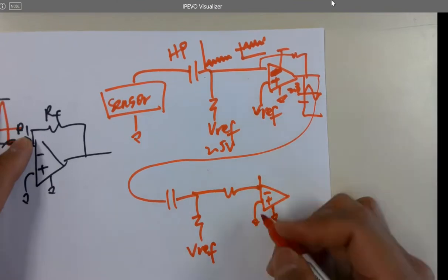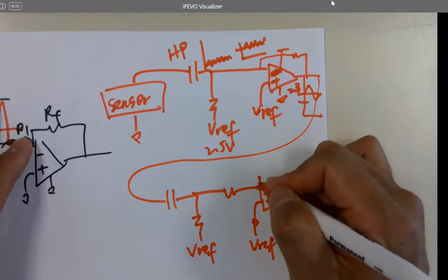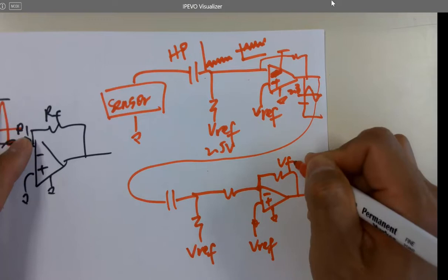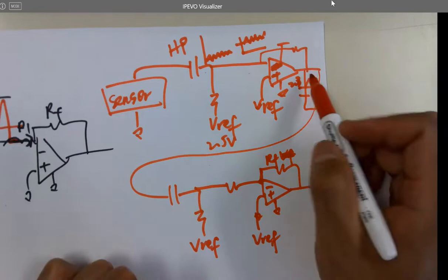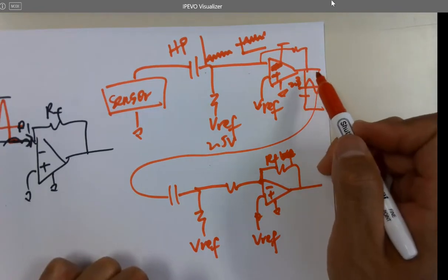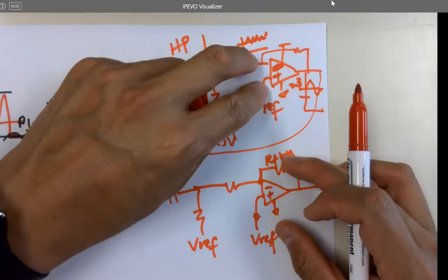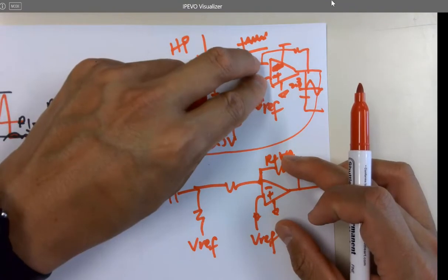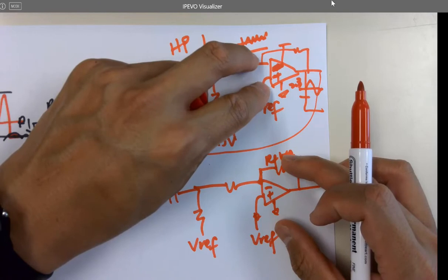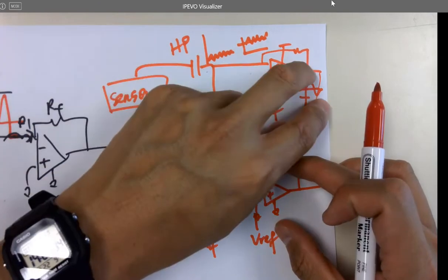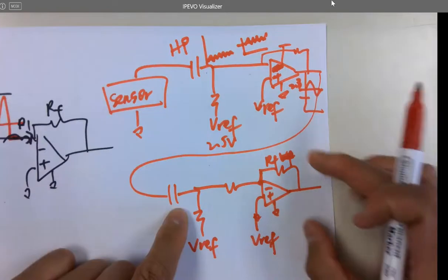If you know your signal won't be amplified out of your range, could you instead of putting a high pass filter in between each one, just put a high pass filter at the beginning and at the end of all of your amplifications? Because you have noise amplified here as well. It's the undesired DC offset being amplified. They are not ideal OpAmps, so there will be some DC difference here, which will be amplified. That's why you don't want to amplify the signal immediately to a very high gain. 10 times, you get a decent signal, remove the offset, and do it again.